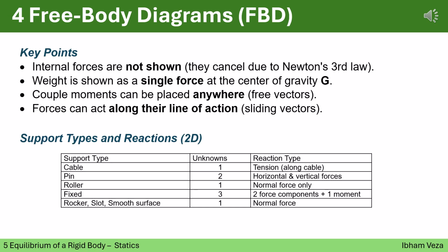Free body diagrams, FBD. Several important rules apply when drawing free body diagrams. Internal forces are not included because they cancel each other according to Newton's third law. The weight of a body is represented by a single force acting at its center of gravity. Couple moments are free vectors and may be placed anywhere on the diagram.